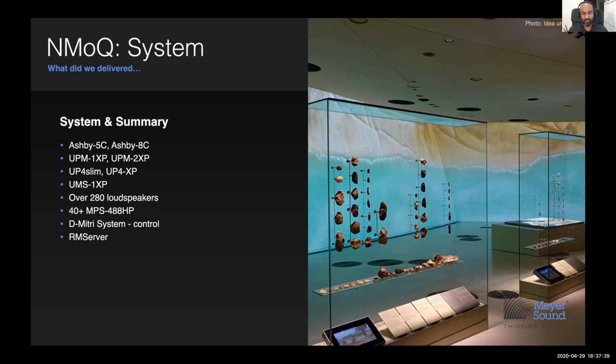And in the same space, we had a mix of loudspeakers because of the way the interior of this place is designed. So if you had to pan sound, maybe you're moving from a loudspeaker in the ceiling to a loudspeaker pretty much on the floor to a loudspeaker somewhere else. And matching voicing for this was very important. Again, emphasizing the fact that having control over loudspeaker voicing, phase, frequency response and consistent performance is really important for immersive audio.